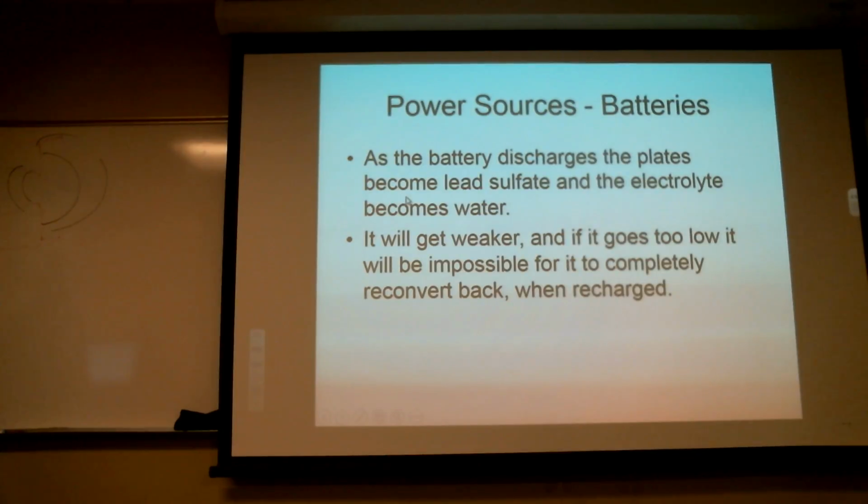Okay? Now, throughout all of this, you're going to have some voltages. And the voltages are going to decline a little bit, and then start declining faster and faster and faster. Depending on the battery type, the way that curve looks is a little bit different. A NiCad battery tends to stay right at top voltage for a long time, and then at about 95%, it goes boom and tanks. Lead acid, on the other hand, sort of stays good, and then about halfway starts dipping down, and then at about 2/3 it starts tanking faster and faster.